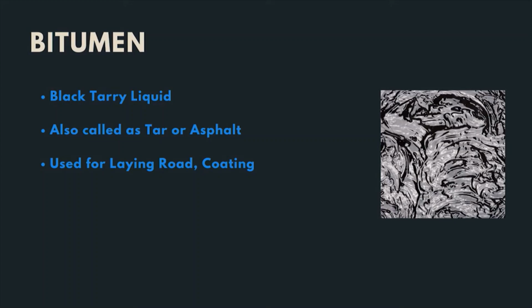Whenever a metallic pipeline is buried by the oil and gas companies, they give an asphalt coating to the pipelines so that water does not affect the pipeline, and the net effect is that corrosion does not happen. And there are some places where the roofs are coated with asphalt. They are known as asphalt coated roofs. And again, here we have different grades of asphalt or bitumen available.